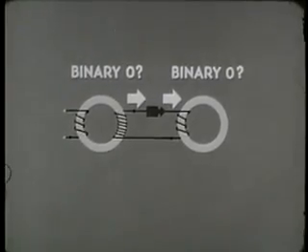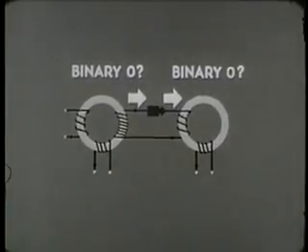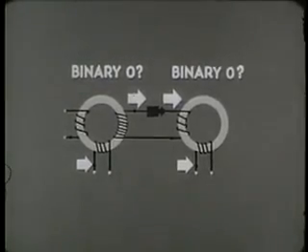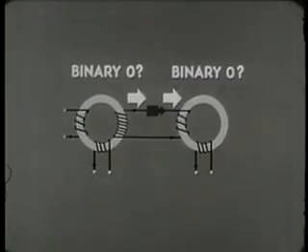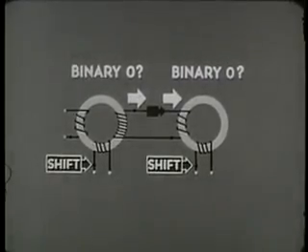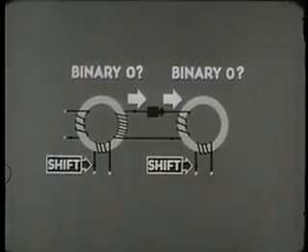What we need for dot current is a shift winding on each core, wound so the dot side is at the left in our diagram. The shift winding shifts or transfers bits from one core to the next, as these two will demonstrate.